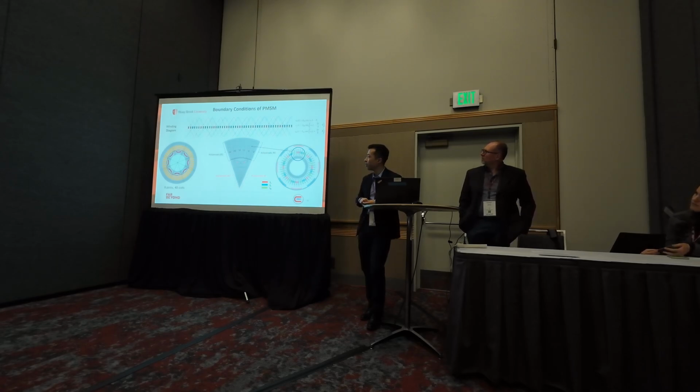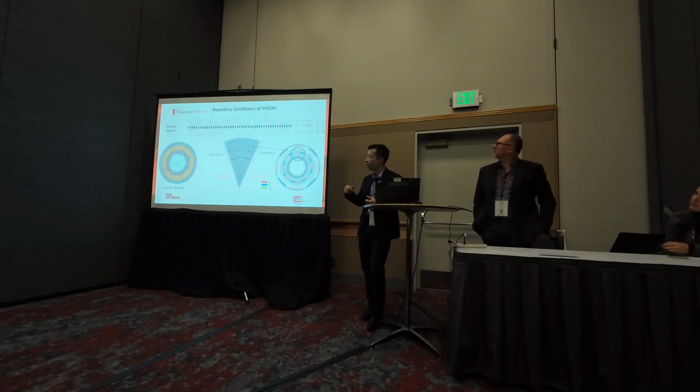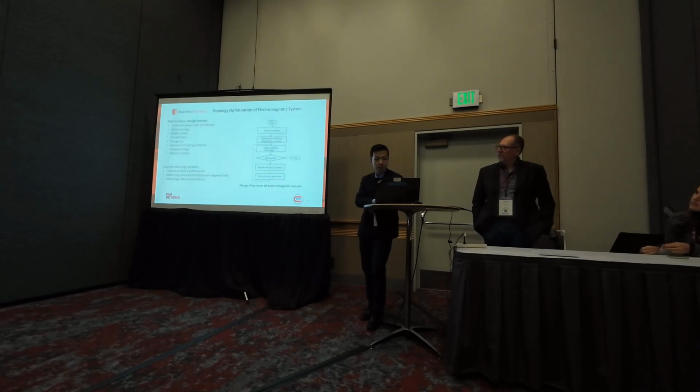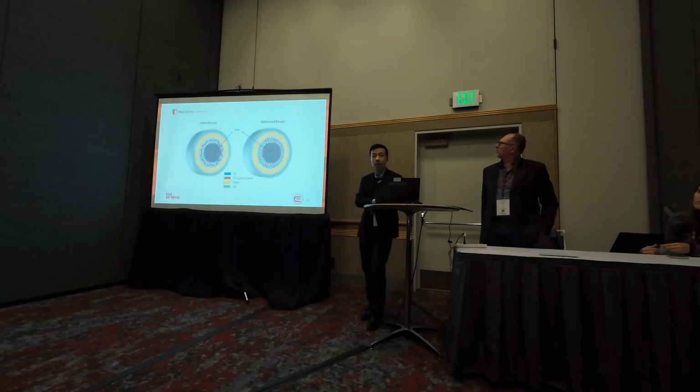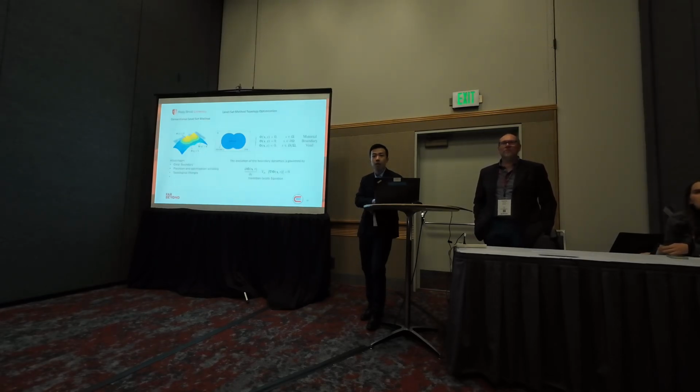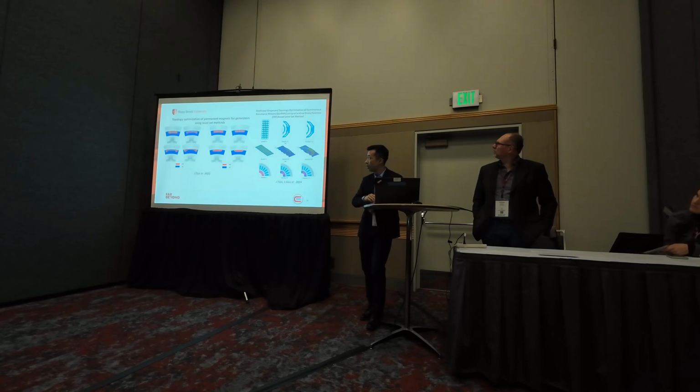So what software do you use? Right here we're using COMSOL Multiphysics. How about the optimization? For this example we use the density-based method, which is embedded in COMSOL Multiphysics. But for our current and future works, we usually write our own code to do the optimization. You use your own code as a plugin for COMSOL? We only export the final result from COMSOL. What kind of algorithm are you going to be using? The level set-based method.